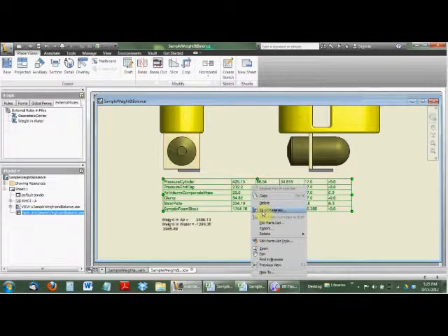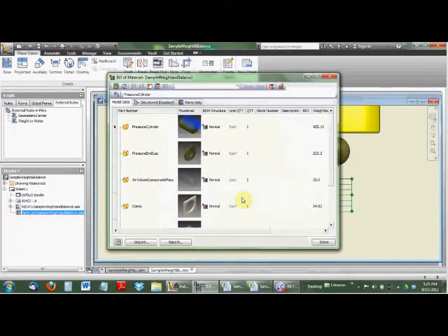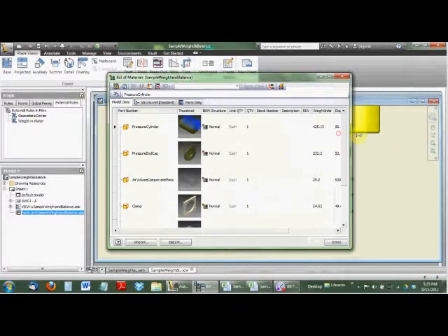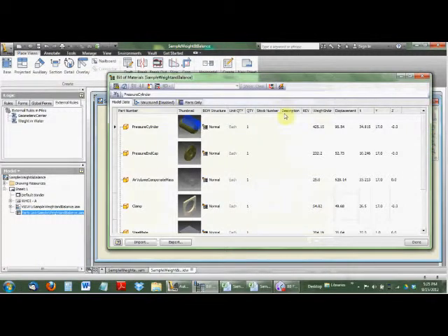So the way you do that is you go to your bill of materials. Now you can go to your bill of materials in your IDW, you can go to your bill of materials in your assembly. And here it comes up. And so we've written the iLogic rules, we've made custom iProperties equal to variables within those rules, and those custom iProperties come up in the iProperties menu.